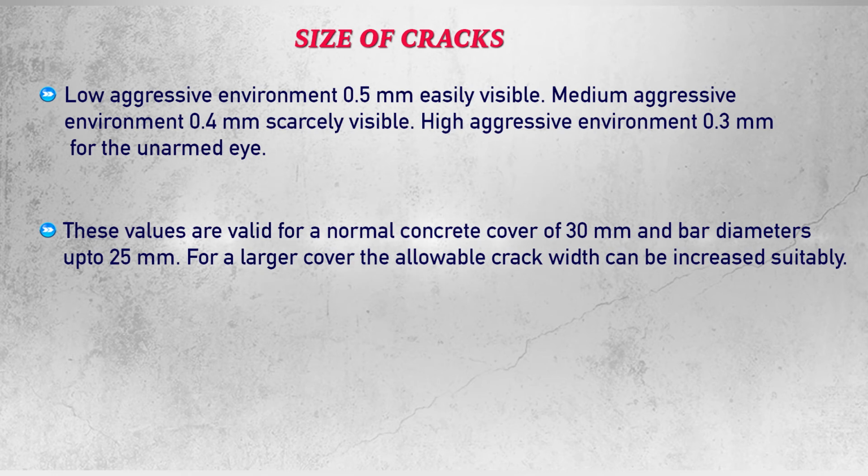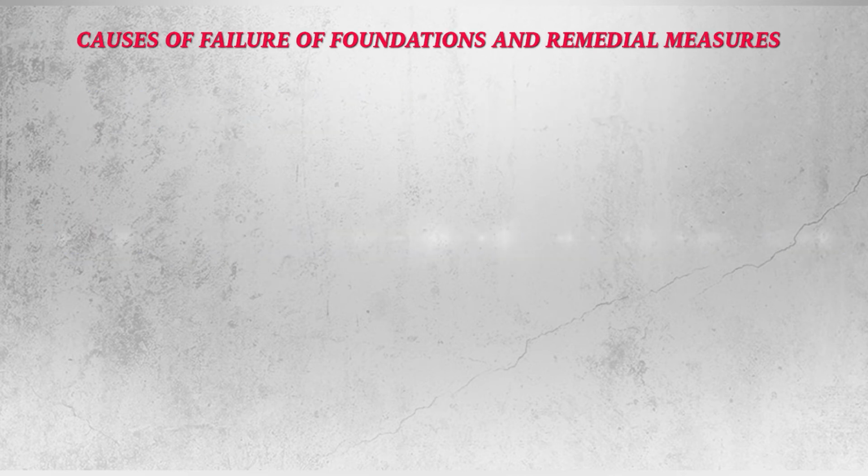These values are valid for a normal concrete cover of 30 mm and bar diameter up to 25 mm. For a large cover, the allowable crack width can be increased suitably. Now let us move to causes of failure of foundations and remedial measures.